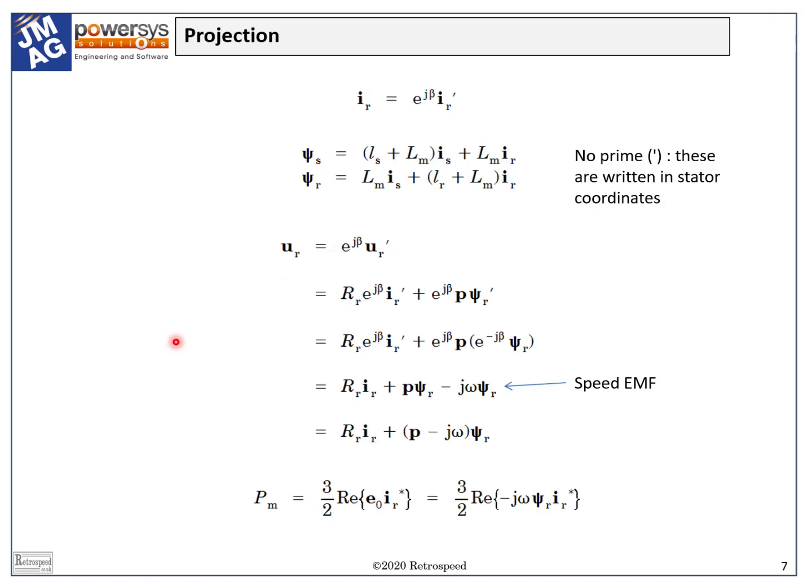The second principle is that when we have two sets of windings, stator and rotor, one of which is rotating relative to the other, we have two sets of space vectors defined in their respective frames of reference. And of course, the flux linkages between the two sets of windings are mutually coupled. We therefore expect the electromagnetic induction of voltage in each set of windings when the current is changing in the other set or when there is relative rotation.